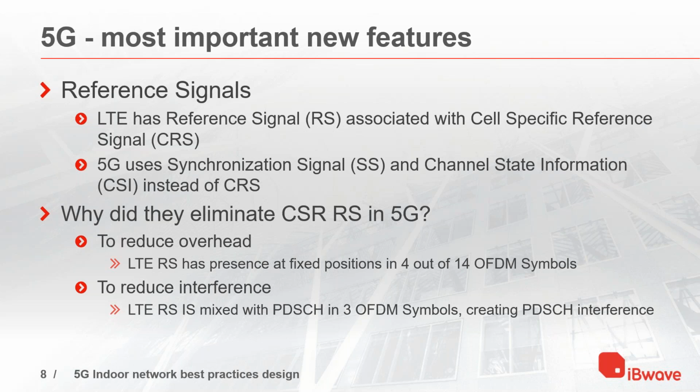Well, the answer is to reduce overhead, because the LTE reference signal is present at fixed positions in 4 out of 14 OFDM symbols. And that is number one.